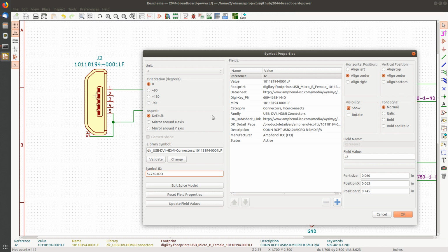board editor? Okay? This is very handy because quite often you do need to re-annotate your project. Maybe you don't want to use single-digit part references. Maybe this thing grows and you want to start them all with J10 or J101 or something like that. How do you do that without confusing everything? Well, if all you do is re-annotate your board and do nothing else whatsoever, you would know that all the symbol IDs have stayed the same while the reference numbers have changed.